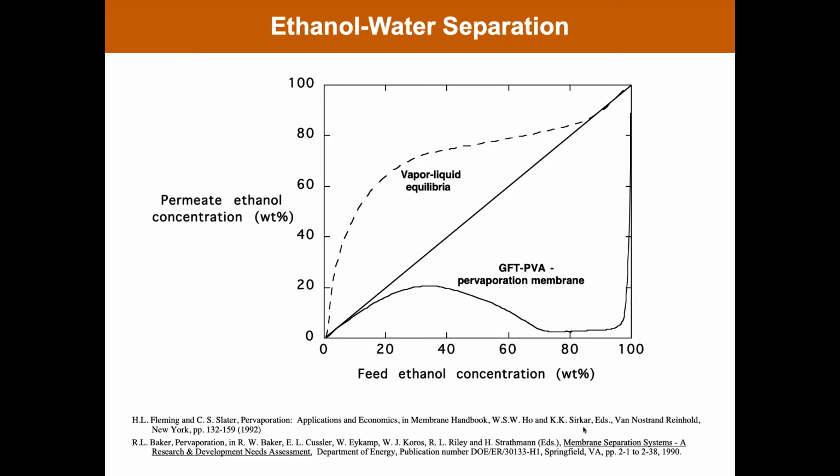They work very effectively for this application, have a long track record, but it's very energy intensive. And there have been people who have tried to use membranes in these applications to reduce the energy intensity. This is showing what would happen with a hydrophilic membrane. A lot of the membranes that are used in this application are hydrophobic, trying to pull the water out through size sieving mechanisms.